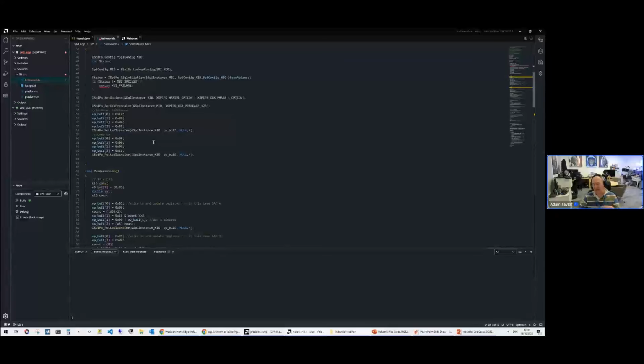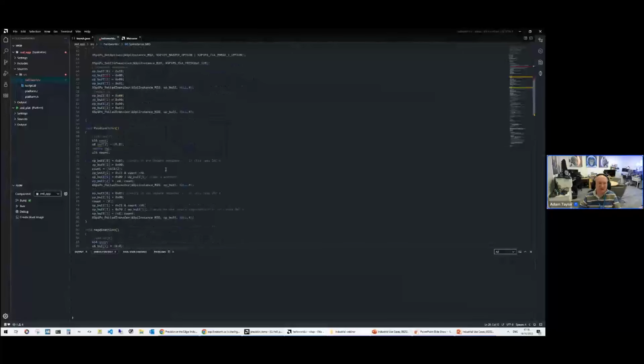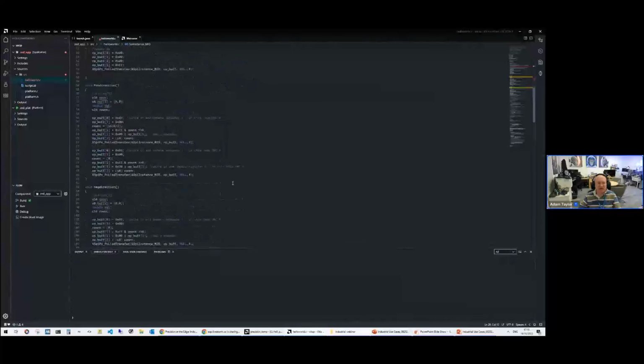So the DAC that's on the PMOD DA4 will do that power up, and this gives us the power up that we can see here, and we can do that transaction there. Again, we do that transaction and it runs nicely. Once we're running, then we define a couple of processes. We've got to write to the registers. We've got to write to DAC A over SPI and to DAC H over SPI, and each one requires a number of